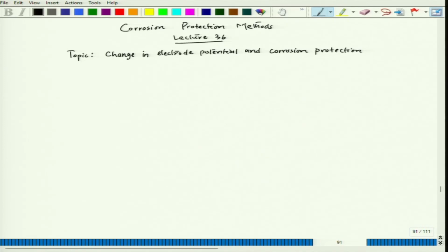Okay. So, let us look at some of the spikes in the current, and then the sudden decrease in the current density once we reach the protection potential, which corresponds to the passive range. Then we will see that the current requirement would be really low. Okay. So, now let us look at some of those values. So, that goes to the throwing power. So, for anodic protection,